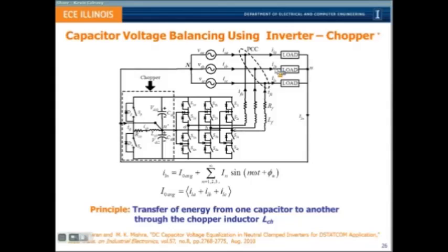Now one can ask, why is that? This is because when the neutral wire is attached to this point, there are certain loads, like the earlier versions of LCD projectors which were using half-wave rectifier circuits which were contributing DC components. And I don't know how many of you use hair dryers. The earlier versions of hair dryers, before 1995, had half-wave rectifier circuits. They tend to draw DC components, which can be clearly seen.